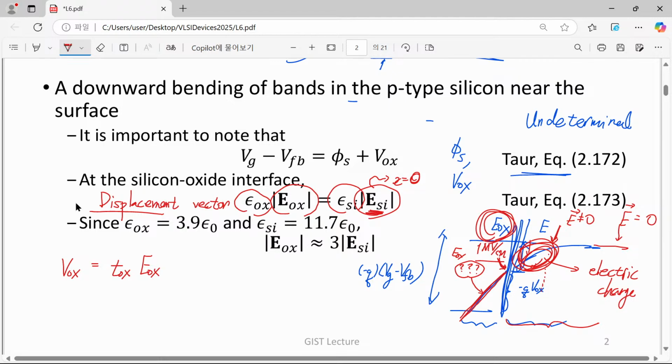So by multiplying by a certain thickness, we can have this voltage difference. Good, but here we have a quantity measured in the oxide field, but we don't want to have this one. Instead of it, we want to express something corresponding to the silicon electric field, and this expression gives us quite a good conversion ratio between our oxide electric field and silicon electric field.